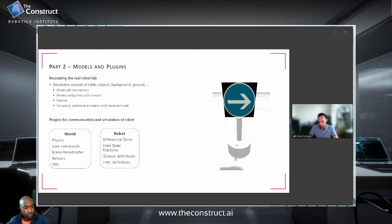And for the robot side, in order to properly use the robot, we first need this differential drive plugin. Because we have a robot with two wheels left and right that are basically taking care of the actuation. This is a differential drive, and in order to move our simulated robot, we have to have this plugin defined with all the information, which wheels, how far are they away from each other, and so on, to properly calculate the dynamics of the robot.